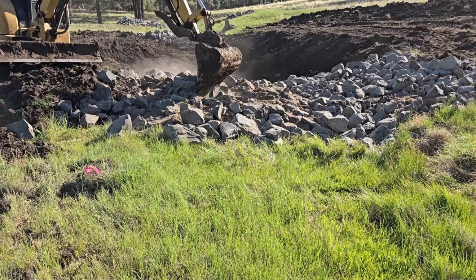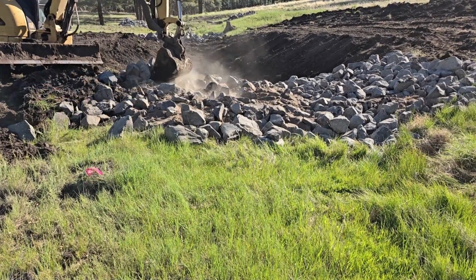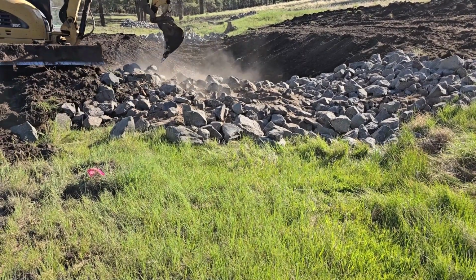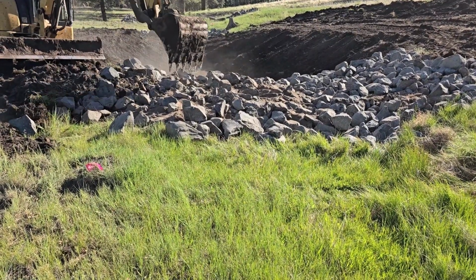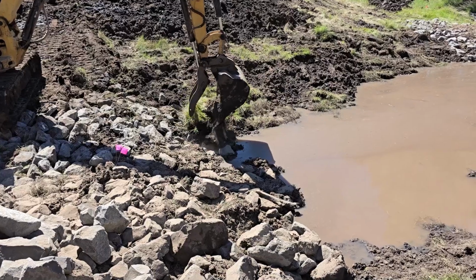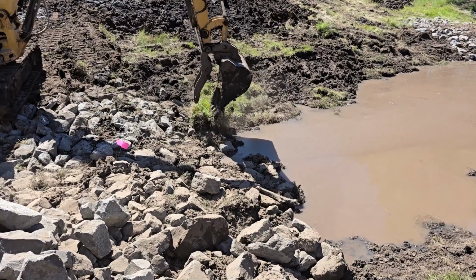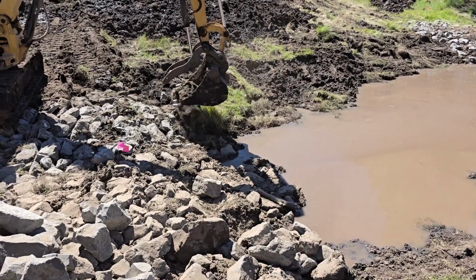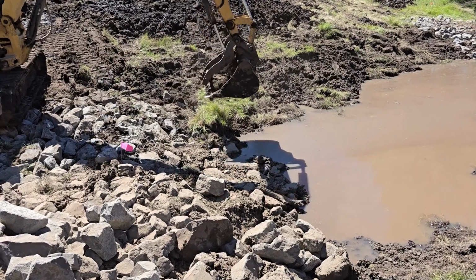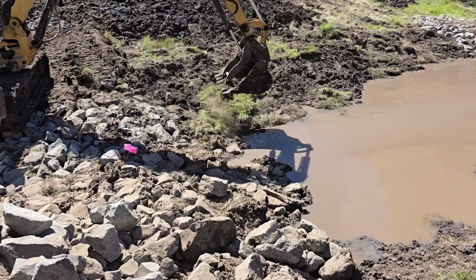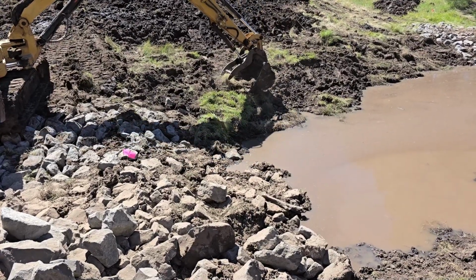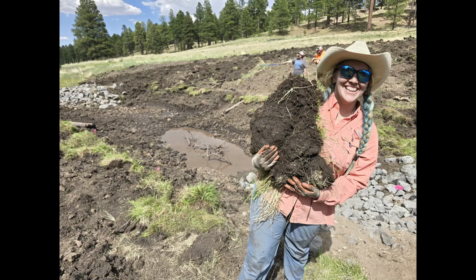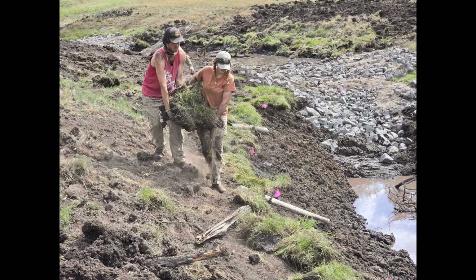One major benefit of using rock to armor the inlet, the groundwater dam, and the spillway is that elk, horses, and cows will not be able to destroy the wetland by causing new headcuts to form. The large clumps of sedge plants that were saved when the wetland basin was restored were replanted using the excavator. The sedges were replanted at elevation equal to the elevation at the entrance to the spillway. This was done so the plants would grow in saturated soil along the water's edge.